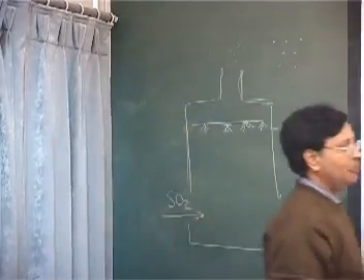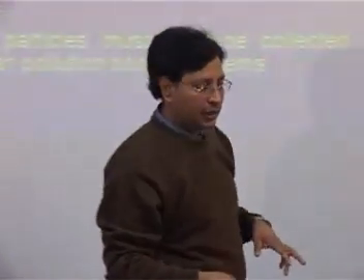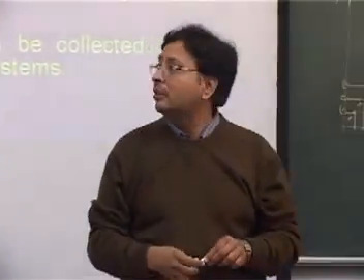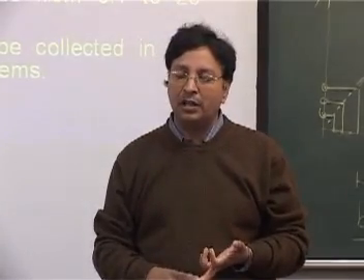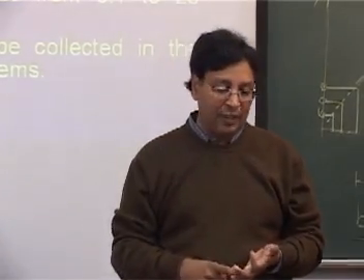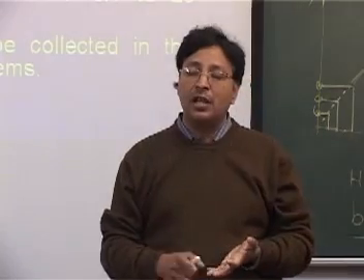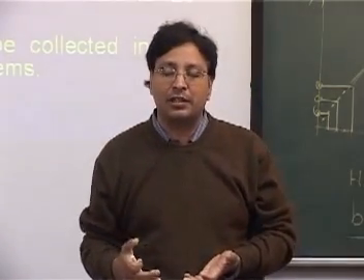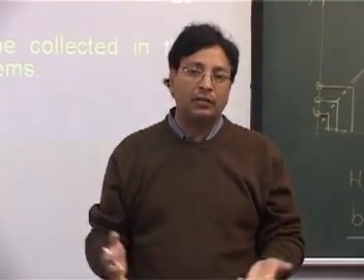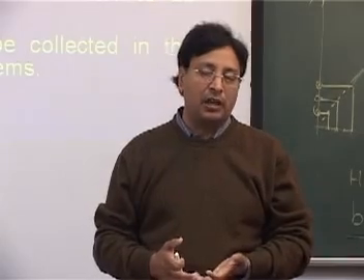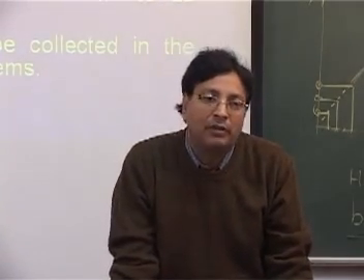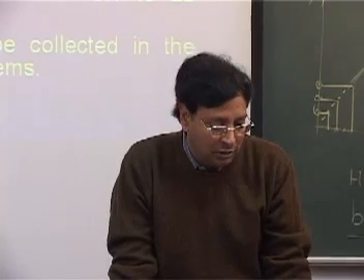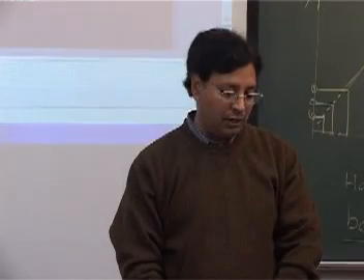We'll discuss a little bit more details of this in the next class, but you can see the mechanisms. The combustion burnout is a different thing, nucleation is a different thing, drop evaporation is a different thing, and ordinary mechanical crushers are a different thing. And that will all give you different particle sizes. And if some particles are formed through chemical reaction, that will always be very, very fine. Okay, we'll stop here.